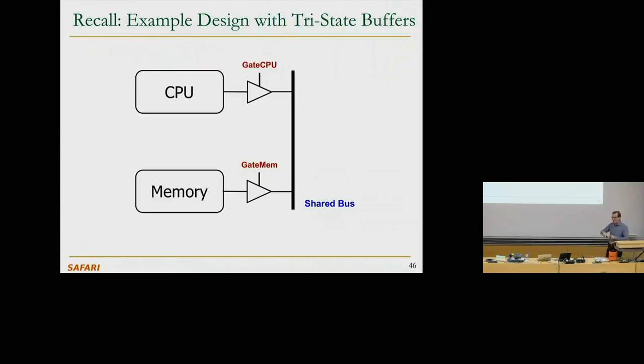And if you remember the LC3 design, it had a bunch of these tri-state buffers, and we will see that even more. So keep this in mind. This is a very important and useful construct. We'll see it tomorrow also, actually, in the timing, because it turns out if you do designs with tri-state buffers, they can be really, really fast. We'll see a MUX tomorrow, a multiplexer that's designed using tri-state buffers. That's much faster than a MUX that's designed using gates. Well, this is a gate also, but using more complicated AND and OR gates.